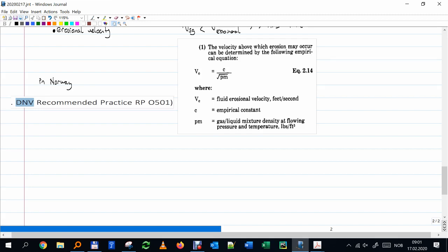If you say that you want 4-inch, for example, what if you drill a slim hole, to try to make it cheaper, to say I don't need a conductor so big and I don't need the production casing so big, but they can be much smaller. But usually you're a bit restricted, and if you need a bigger or smaller 7-inch, then you start playing with the completion part, with the liner, with things that are not hanging on the wellhead, things that are hung much below. I hope that answered your question more or less.